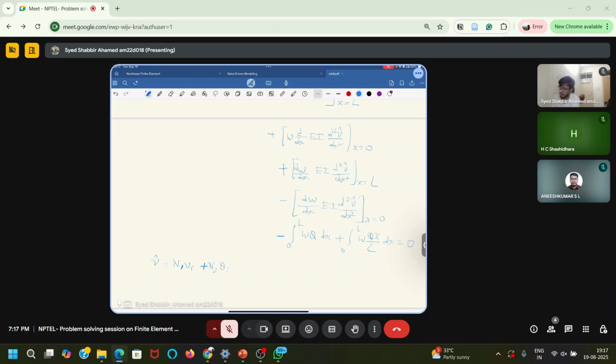In a beam at each point there will be two primary variables, which are the transverse deflection of the beam and also the slope of the beam, which is nothing but dv by dx. So I will take the slope of the beam theta is equals to dv by dx. This is the consideration we will take in the linear Euler Bernoulli beam.